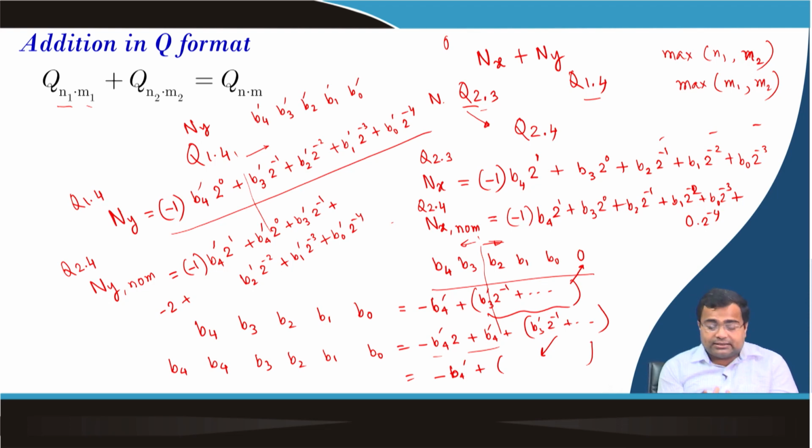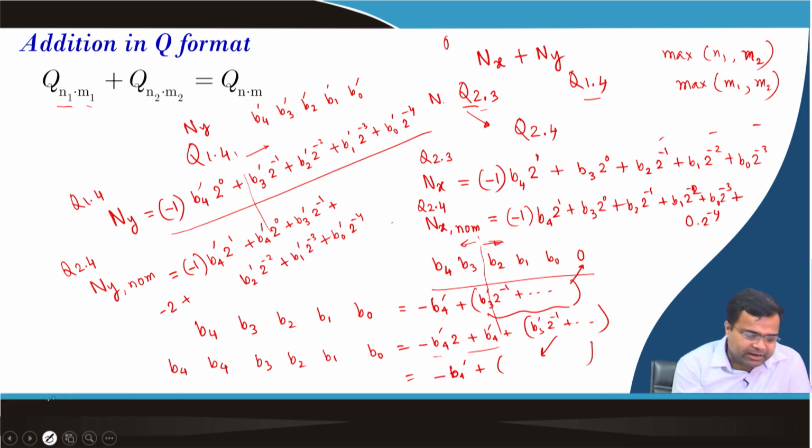That means, in 2s complement we can simply extend the sign bit. So, we can resize this data by increasing the MSB, just simply extend the sign bit, and that is a common practice. So, the sign bit extension does not change the value. Similarly, the extension with padding with 0 in the LSB does not change the value. So, that means we can resize this data in this format.